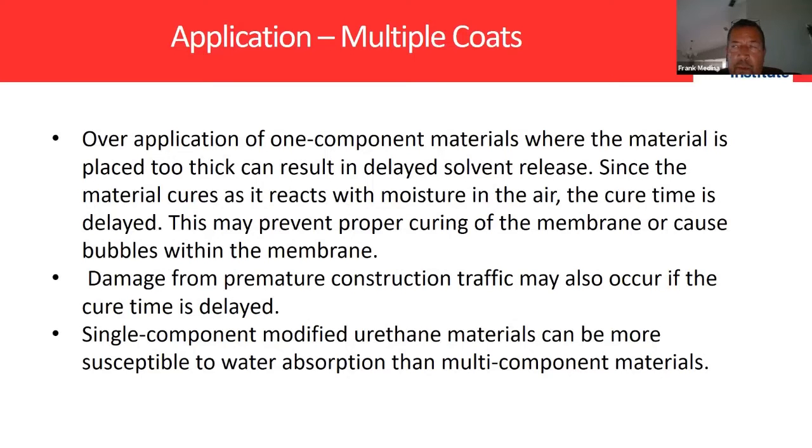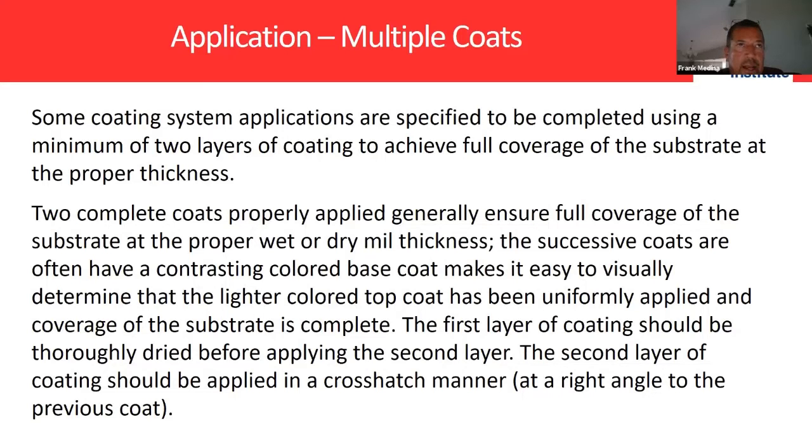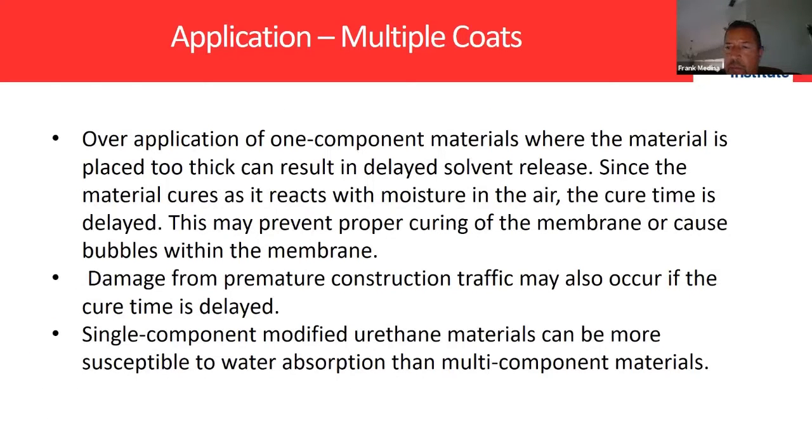So prior to that, I went back into some moisture testing on the concrete, drilled some holes down to 1 inch. And I found that there was moisture in the concrete. It ranged from 16% to 26% in other areas. So we're waiting now for Tremco to come back out, and they have a solution, but they're not really saying what it is yet. Once they come out, they're going to do their solution in a 10 by 10 foot area, wait a couple days, and then see if that's going to cure the problem. If it does, then we can move forward and remove the roof system that we installed and install new material.